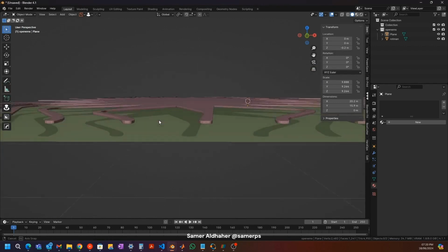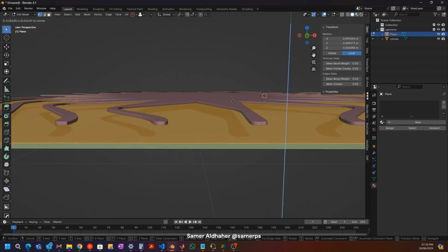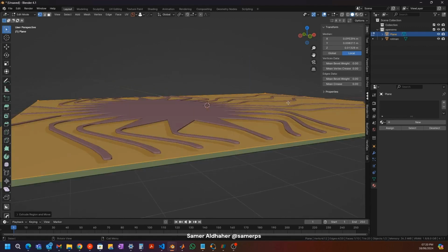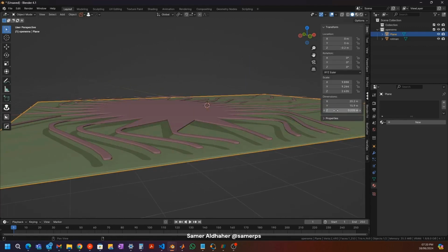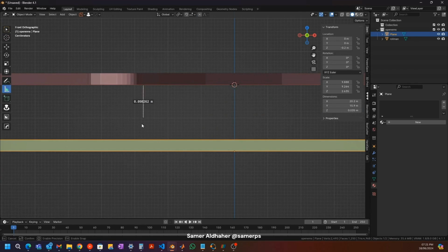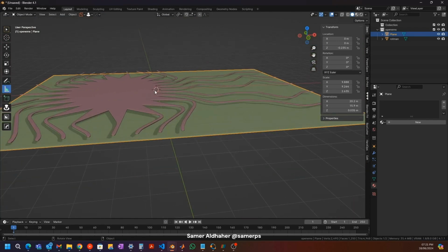Okay, and let's give this some thickness as well. So let's go to edit mode and give it some thickness, and also let's say 0.35 as well. Now, of course, the distance is not going to be 200 micron, so this is from here to here. You can see that because we've added the thickness, and to fix that we need to subtract the thickness of this, so 35, and now this should be 200 microns or so. Okay, so that's our ground plane, and let's call this ground plane.